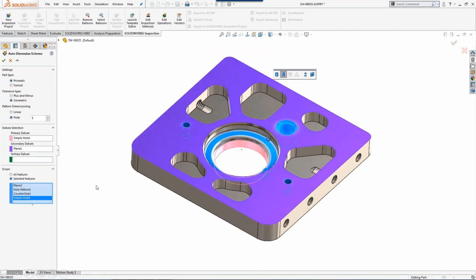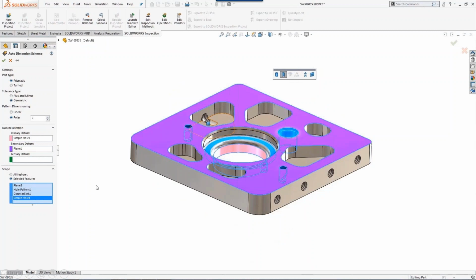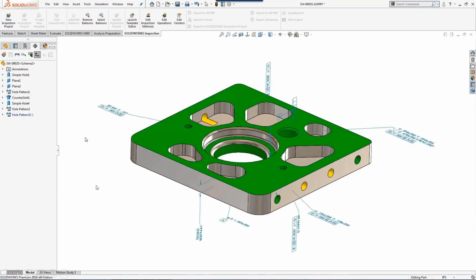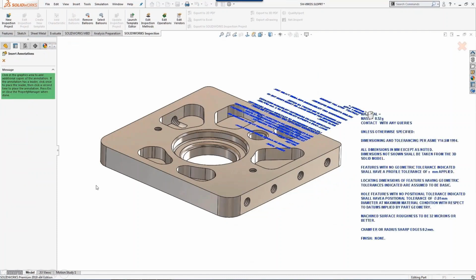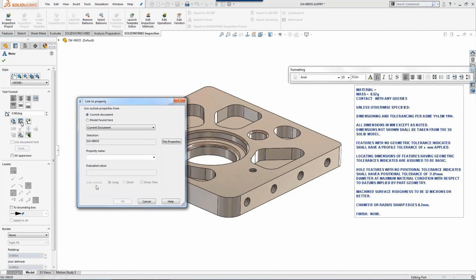And also it will show you the status of the tolerances by giving you green, completely defined features, yellow, not completely defined. But you don't actually need to define everything because, for example, those pockets don't need a very tight tolerance, so you can insert a general note and insert a general tolerance surface profile for this model, and it will be okay.